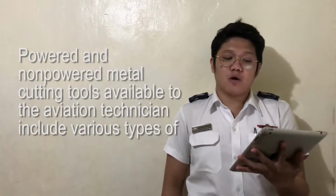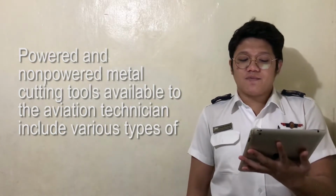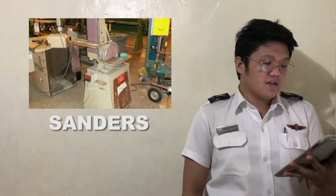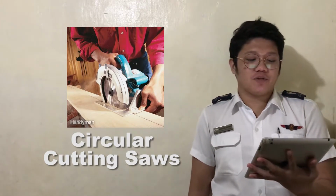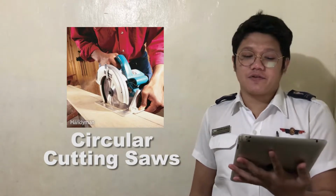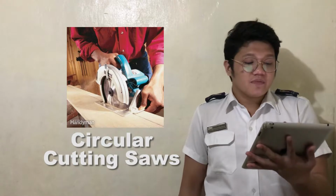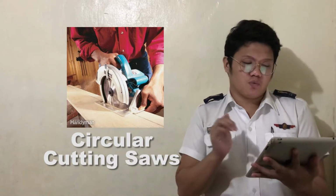Now let us proceed to the cutting tools. I will discuss the powered and non-powered metal cutting tools available to the aviation technician. These include various types of saws, nibblers, shears, sanders, notchers, and grinders. Circular cutting saws: the circular cutting saw cuts with a toothed steel disc that rotates at high speed, handheld or table-mounted, and powered by compressed air. This power saw cuts metal or wood.